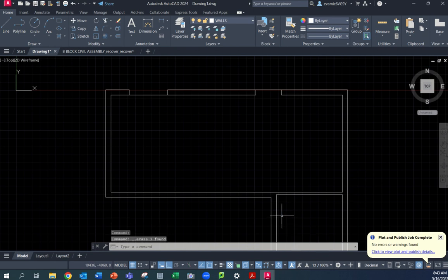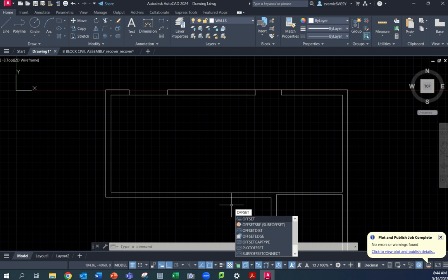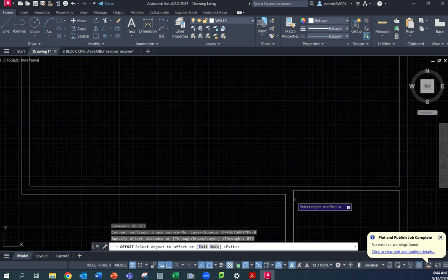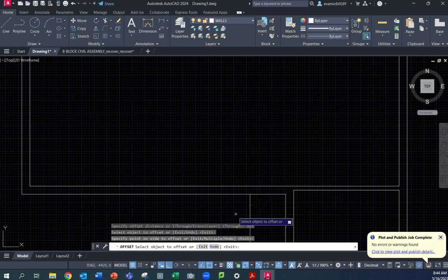Right, now we're going to move on to the positioning of window 2, which is over here, and we're going to use the inside edge over here. So this little corner here, this line here is what we're going to use. We want to offset a total of 875 from there. So we're going to go offset, and we're going to go 875. Now it's probably better that I left this line a bit longer, but it's okay. So I'm going to come across 875. The window width then is a total of window 2, so it's 1500. So it's a number 2 window, so 1500, there it is.